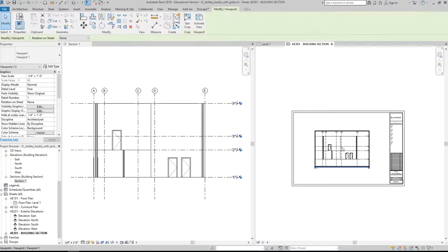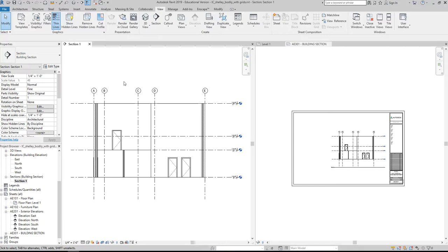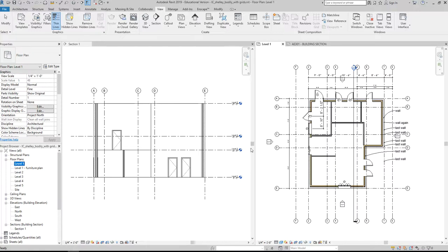All right, I'm just going to nudge this little guy over a bit, because the next thing that I'm going to show you how to generate is a wall section. Okay, and a building section is probably best placed in a floor plan, right? I'm going to go back to my floor plan view real quick, because I can run them all the way through my building this direction. I can run one in the opposite direction if I wanted to, right?